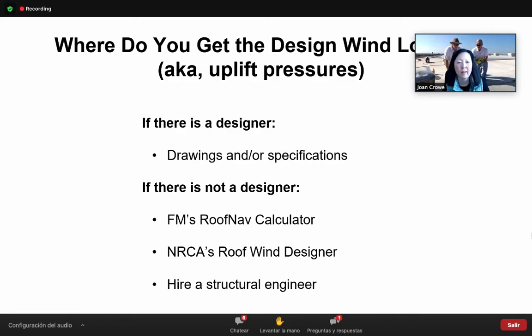So if you don't have a designer on board, like in a re-roofing where unfortunately the contractor has to do some math, there are several options. There is the RoofNav calculator. The only problem with the RoofNav calculator is that you're going to get a little bit higher pressures because FM is an insurance company.